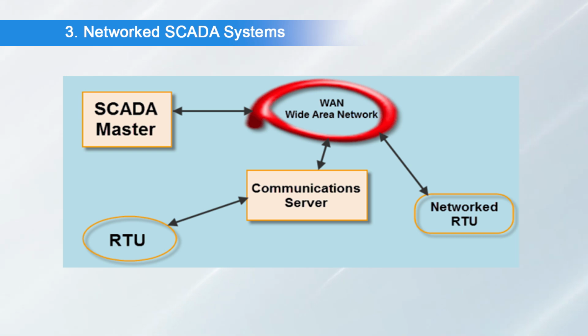This means that the SCADA system could now be used not only in a single plant, but throughout several plants with physical locations far or very far distant from each other. With this network architecture, the data and the supervisory control can be accessed anywhere, even from a physical location different than the plants.